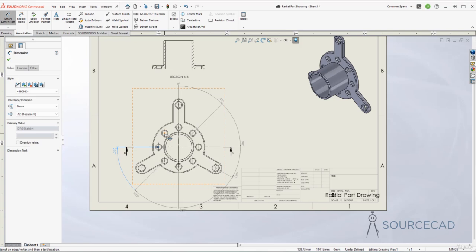Not only that, you can also select axes if you want. For example, here I've just selected the intersection point of axis and here it is, the angle is added. So you can just add these angular dimensions like so. But here also we have a problem. And the problem is all these extension lines. So these extension lines are still making our drawing kind of cluttered.